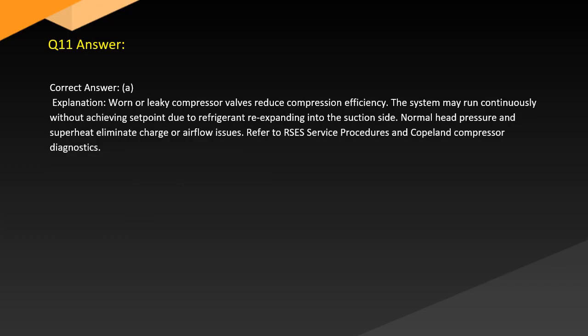Answer. Correct answer A. Explanation. Worn or leaky compressor valves reduce compression efficiency. The system may run continuously without achieving set point due to refrigerant re-expanding into the suction side. Normal head pressure and superheat eliminate charge or airflow issues. Refer to CESA service procedures and Copeland compressor diagnostics.